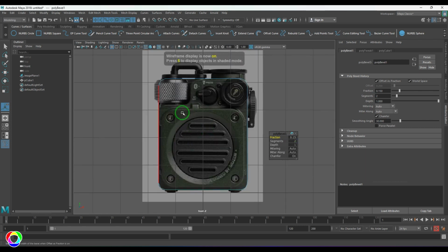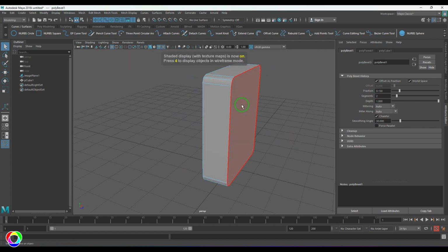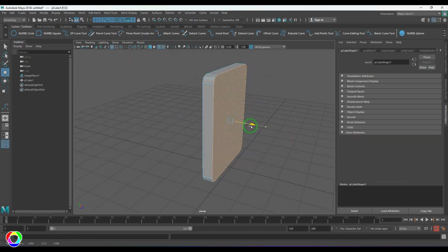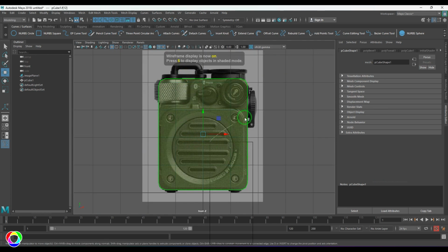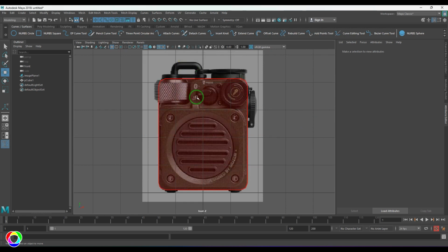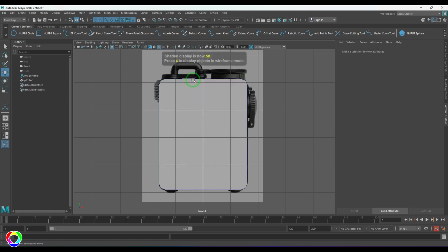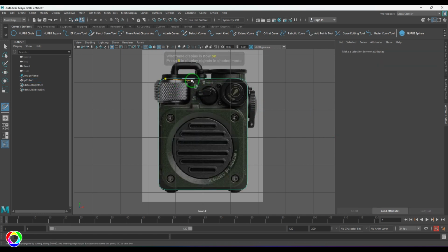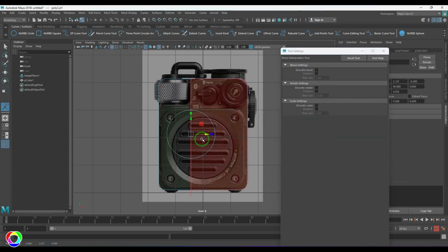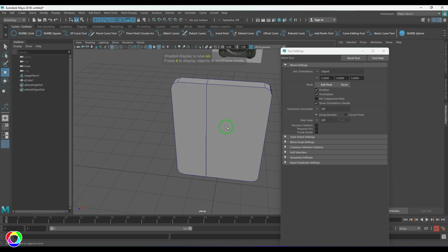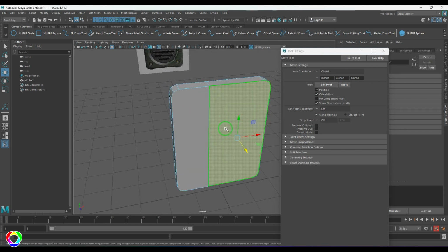The next thing is it has got some thickness, so let me select that face and maintain that thickness there. Once that is done, we need to extrude that line and that line. This and this line have to be added, and then I need to round it again. I'm going to use the multi-cut tool, and I need to choose the option called plane. I'm using the YZ plane, and then move it like that, and I get a line. I could have used insert edge loop, but this is no loop because this is an n-gon.